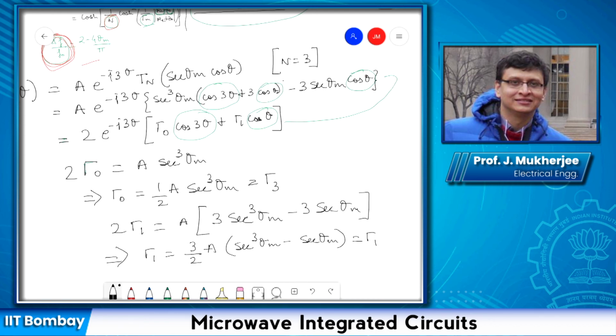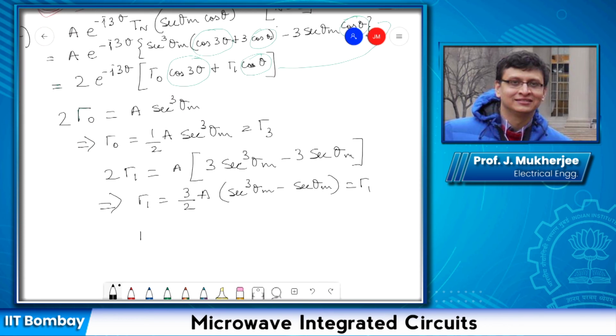Okay, and then we know that gamma k is equal to half ln of zk plus 1 upon zk. This simplification is taken again, once again, for getting consistent solutions. So here now you substitute the values of this gamma 0, gamma 1, and then using this equation you can find out the values of Z1, Z2 and Z3. And in your notes, I have given a problem. Please try to go through it and see how it is solved.